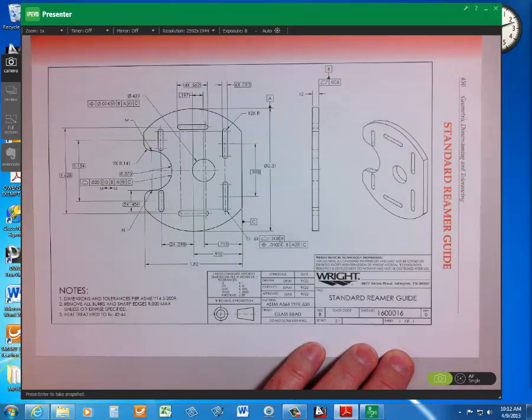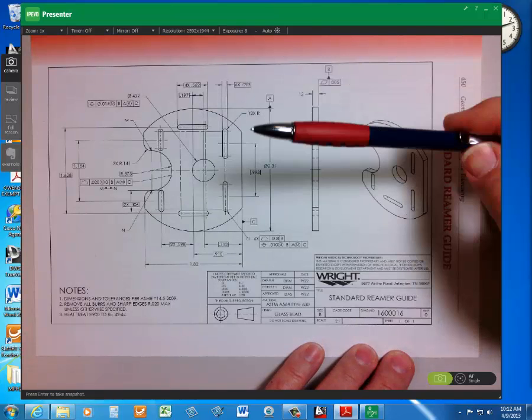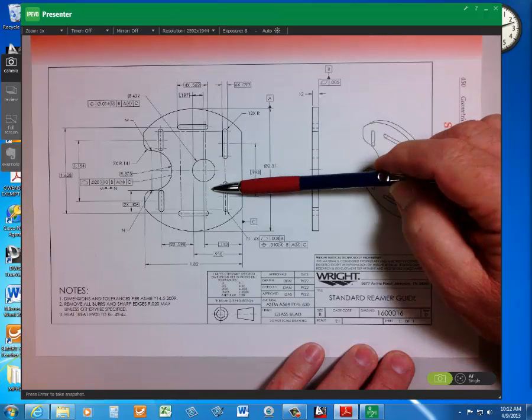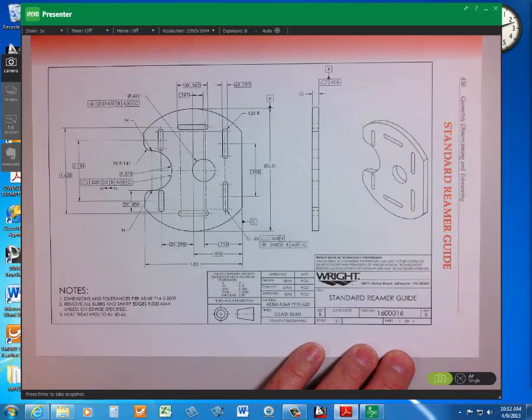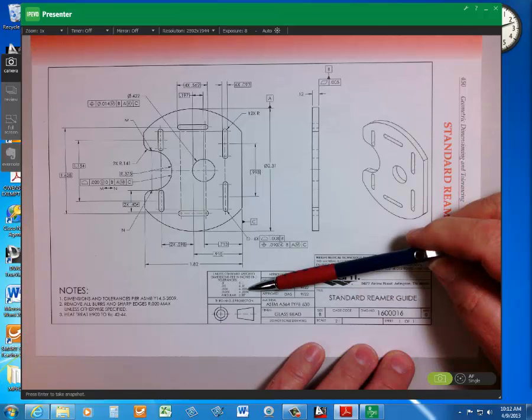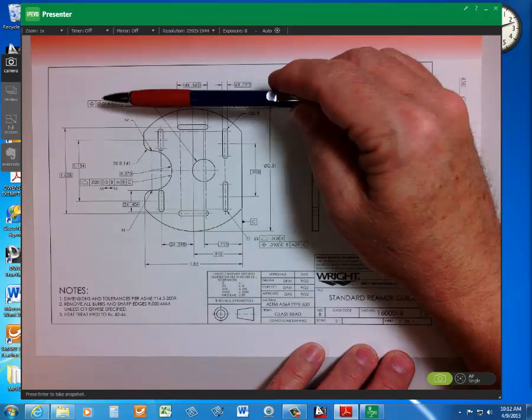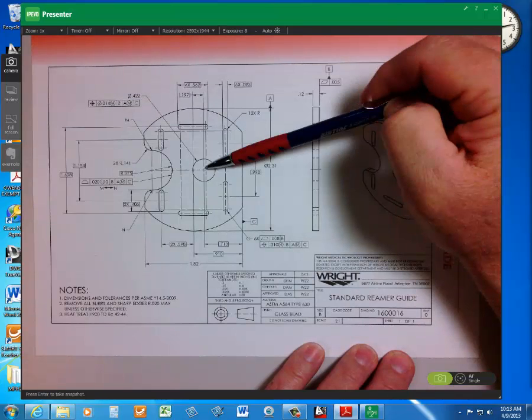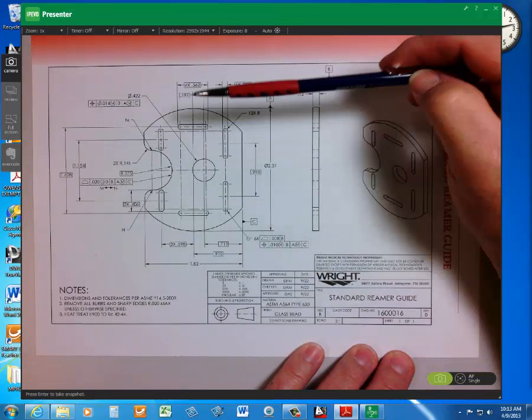The positional tolerance and virtual condition. Okay, so it's a hole, so holes at its smallest would be MMC. So that's 0.417 using this tolerance block. Your position tolerance is 0.014, so we subtract because it's a hole. So our virtual condition is 0.403.